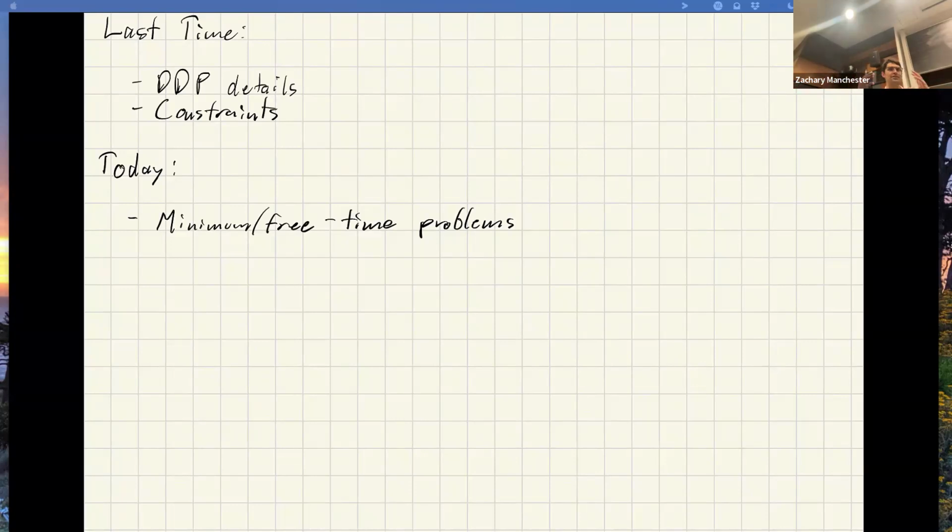There's a lot of literature on that. That's a pretty special case. In a lot of cases, we get what we call bang-bang solutions, which means you slam your actuators full gas and then slam full brake the other way. You get this switching-style controller, and that is time optimal in a lot of cases. So these problems show up. We're going to talk about how to write those down and solve them numerically within the context of what we've been talking about. And then we're going to do the direct trajectory optimization story.